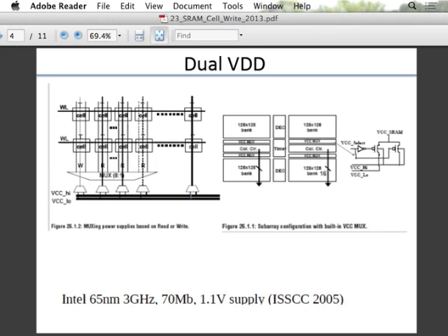So now the threshold voltage and the body voltage, that relationship, it turns out there is about 1:10. That means if I want a 100 millivolt change in threshold, I need about a 1 volt change in the body voltage. In fact, as processes scale down, we want less and less impact of the body on the threshold, because you want only the gate to be the main controller, master of the channel. So the body's influence on the threshold voltage in deep submicron is much less, and you have to put in a lot more voltage to get 100 millivolt.